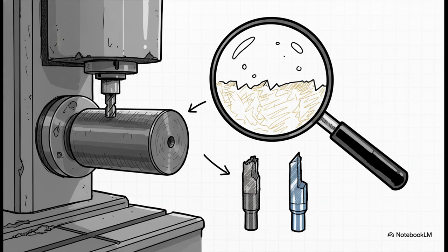And that brings us to a stark, unavoidable reality on the factory floor. Perfect parts are physically impossible. Let's say a blueprint calls for a 20mm dimension. Well, natural variability in the cutting machines, the daily wear and tear on the tools, and even human operators mean that producing two parts that are perfectly, exactly 20.000 millimeters is literally impossible. The real size is always going to vary.